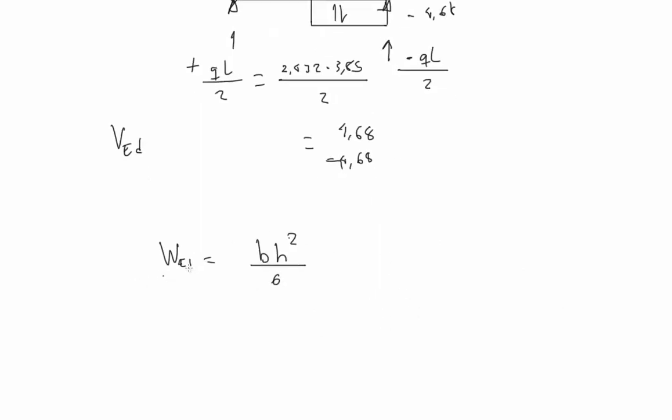I assume this is the maximum work of the elastic. Whatever, that's what I want to find out. I used the right terminology, because again, remembering numbers and formulas is a bad way to understand something. Anyways, so the W elastic is equal to the base times the height squared divided by 6.